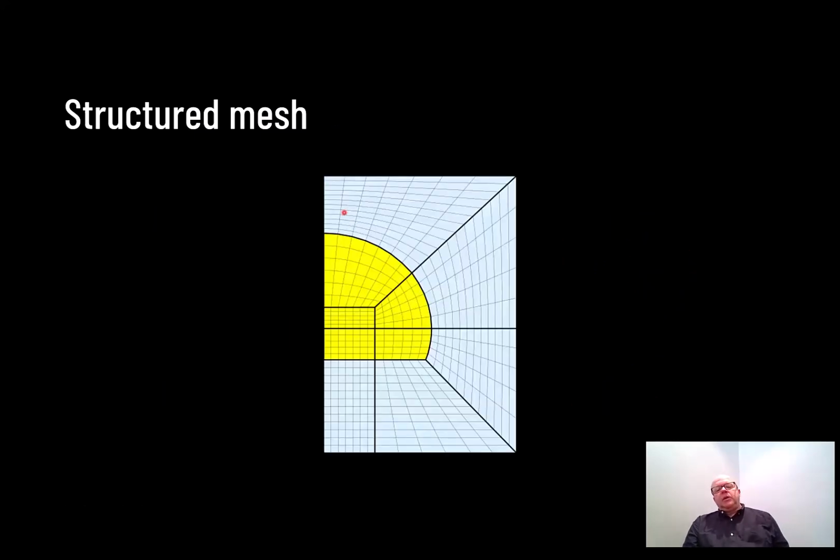And you might think you can be limited by using structured mesh generation, but it's kind of a way of using super elements to build your geometry. So in this case, this is a tunnel opening, half of it. So there is a symmetry line here on the left side. And then you have this four-sided super element to build up the structure here. The important part when using this is that the connecting lines here must have the same number of elements to be compatible. But you have very good control of exactly how the mesh will look using this kind of approach.